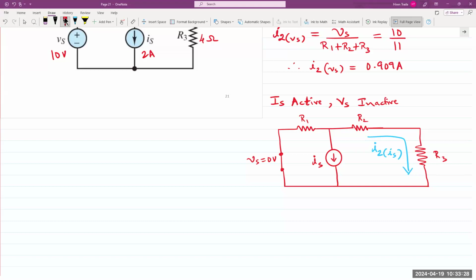If you take that same power supply and you run it in constant current mode, it is now a current source. So in real life, they are one and the exact same thing. The box is exactly the same thing. A power supply unit can supply voltage and current. They cannot exist without each other. If you're supplying voltage, you are supplying current. If you supply current, you are supplying voltage. If you run that power supply in constant voltage mode, it is a voltage source. If we run the power supply in constant current mode, then it is a current source.